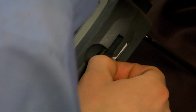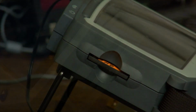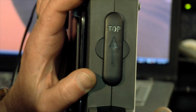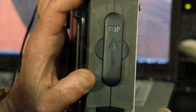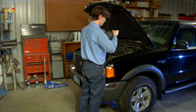Remove any smart cards from the Scan Tool. Remember to store all smart cards in a safe location for future use. Replace the protective cover on the smart card slot, and then install the protective cover in the memory card slot. To avoid damaging the memory card, make sure the arrow on the top of the cover points toward the top of the Scan Tool. Your OTC Genisys Scan Tool now has the latest operating software and is ready for action.